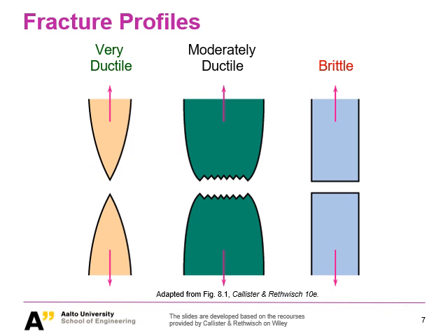And if you try to make some schematic drawing, you can see on the most right we have the brittle fracture. That is also a schematic drawing of a tensile specimen. And in the middle is something we usually see from our tensile test. It is already ductile, but we usually call it moderately ductile.